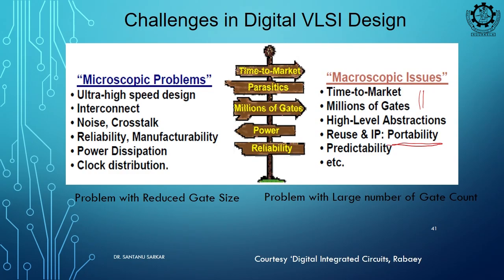Suppose your previous design was in 180 nanometer and you are moving to 22 nanometer or 40 nanometer. Can you port the previous IP to the new technology? Is it easily portable? All of these issues will define how quickly you can make the next version. If the previous IP is portable, meaning it is technology independent, then your job is a little bit easier, right. You can directly use the previous IP or use it with little modification.